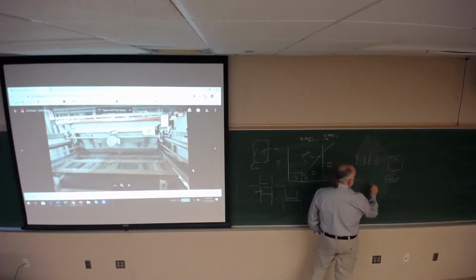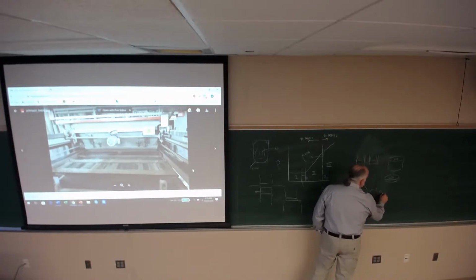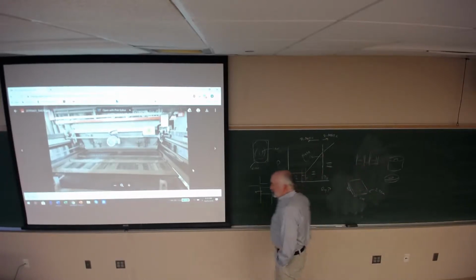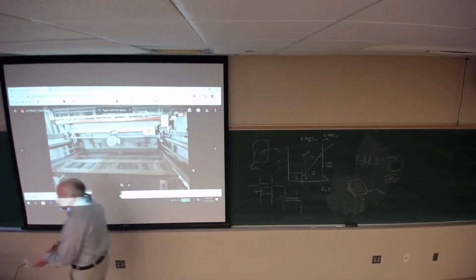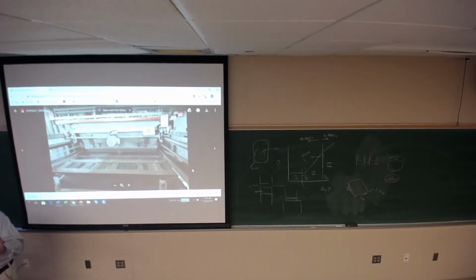I made it too thick. So your thickness is about 2 to 3 centimeters. On the really, really large tile compaction presses, they do not have an outside die. They simply uniformly load that powder and they press it this way, and there's no lateral movement to speak of. The edges aren't perfect, so then it goes through the kiln, and then they trim the edges after pressing.